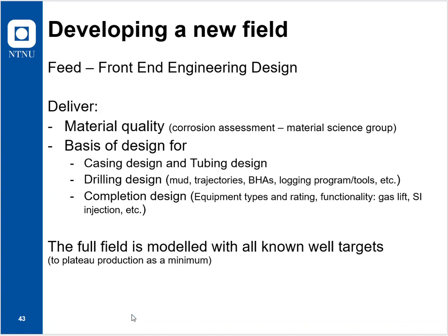Typically, once you have scoped the number of wells and you know that part, that's typically front-end engineering design too, the number of wells and their designs, then you need to contract suppliers of Christmas trees, tubulars, or casing, tubing, liner, called OCTG, Oil Country Tubular Goods. You need to contract all of them and have these things delivered, and you need to do that very often minimum 1 year in advance, because that's the lead time of these items.